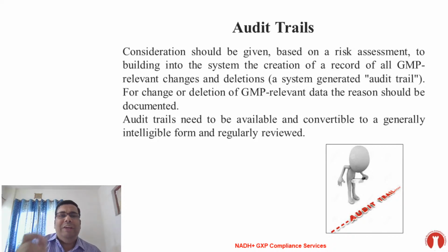So we have to do the risk assessment when building the system, with creation of a record of all GMP relevant changes and deletions. For change or deletion of GMP relevant data, the reason should be documented. Audit trails need to be available and convertible to a generally intelligible form and regularly reviewed. So there is no specific frequency of the audit trail.